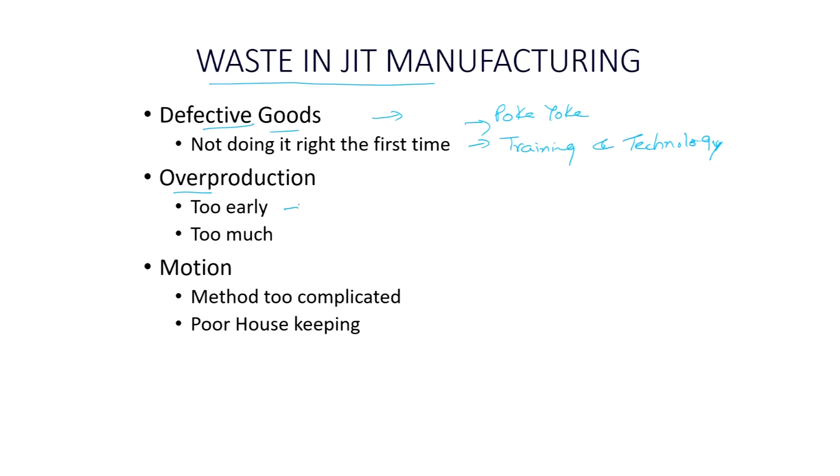Your material needs to be supplied on Friday and you have produced it on Tuesday. So, for the next 3 days you have to find storage space to keep this material. That is a waste; all storage is a waste. Say the demand was 500 units and you have produced 550 units. These 550 units you have to keep in stock till you receive the next order for the same type of product.